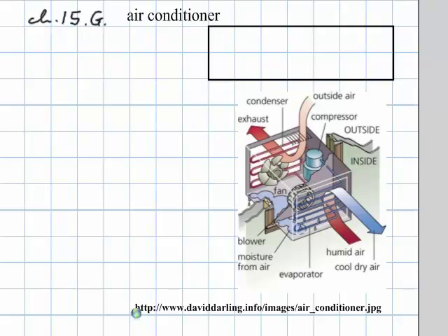Okay, what's given is the high temperature, that is outside the house, 311 kelvins, that's 38 degrees Celsius. Whoa, this is like 110 Fahrenheit outside. And inside the house, it's 297 kelvins, 24 Celsius, or in the neighborhood of 80 Fahrenheit inside the house. So the house itself is already pretty warm. But we need the Kelvin temperatures anyway, so I didn't have to convert them, I just did that to illustrate. Then we're supposed to figure out what the COP is.